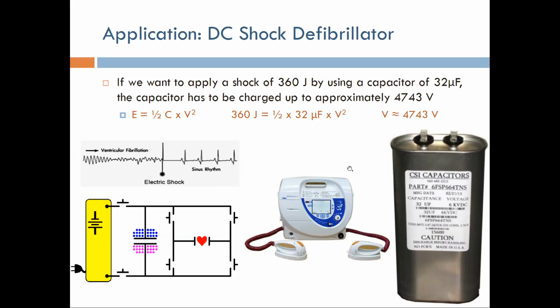Okay, so basically this device is just based on a capacitor. It has a capacitor that looks like this actually. See how much capacitance? 32 microfarads. And the withstanding voltage here is what? 6K? DC, 6K volts, 6,000 volts.